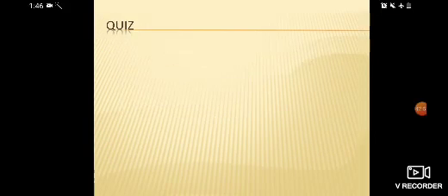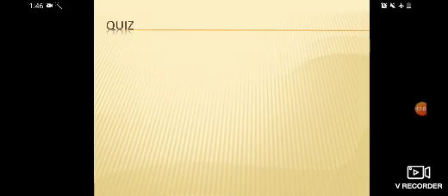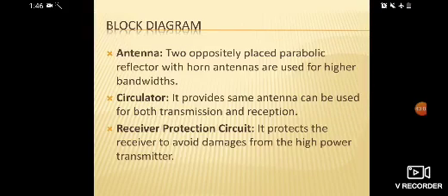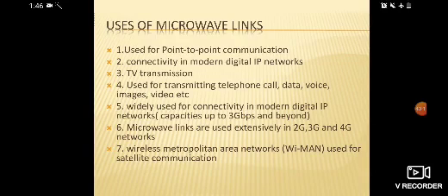It performs the same function as a copper wire, a coaxial cable or a fiber optic cable, but in a different manner, by using point to point microwave transmission between repeaters. The microwave link receives the transmitted signals from the microwave transmitter, amplifies them, and then retransmits them.